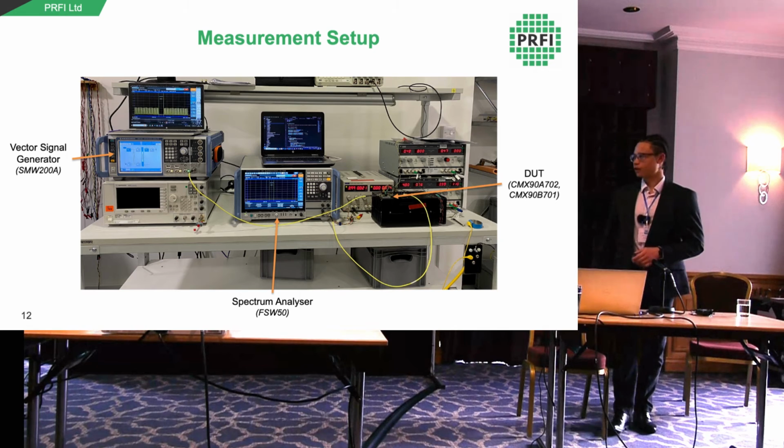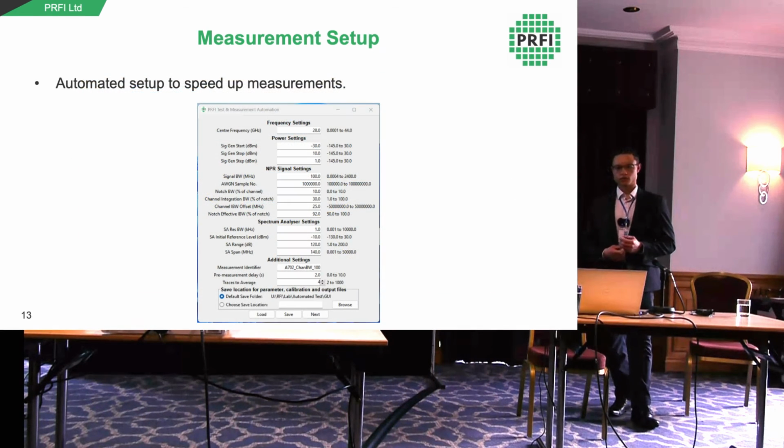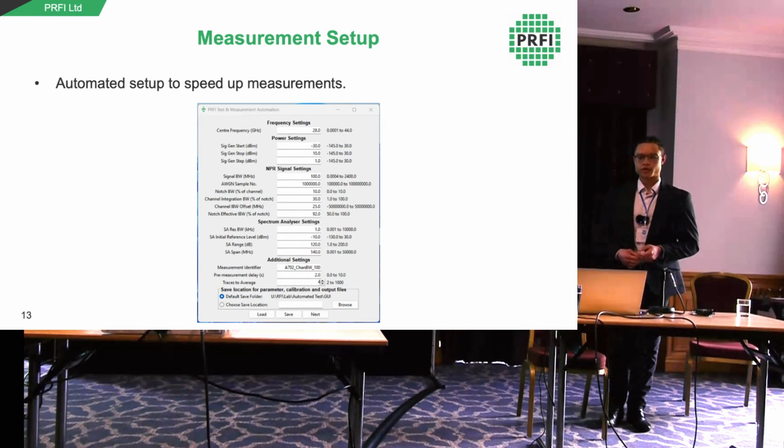And then briefly, we took measurements over a lot of different frequencies, channel bandwidths, and notch widths. So we automated these to speed up time. And this just shows the settings screen for our measurement sweeps, the sweep settings, and then the settings on the signal generator and the spectrum analyzer.